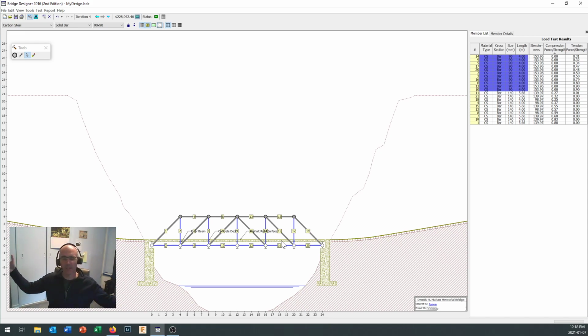As you get to bigger and bigger bridges, the weight of the traffic on it really does start to approach insignificance. And in fact, what you'll find on truly large bridges is that the design factors for live load are far less significant than for seismic load, designing for earthquakes, and wind load, designing for the wind blowing across it.